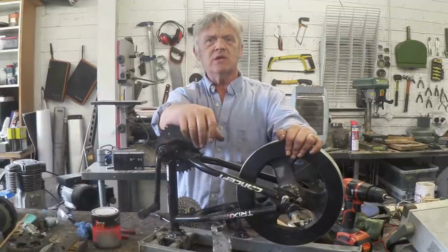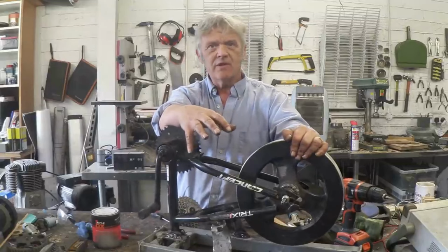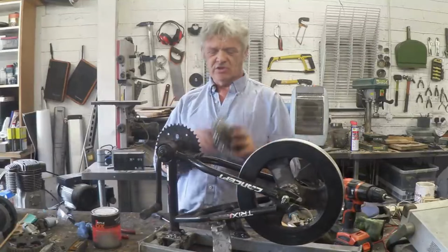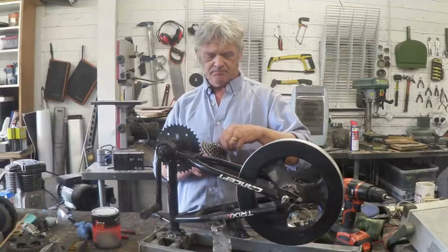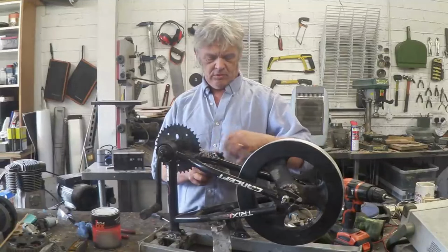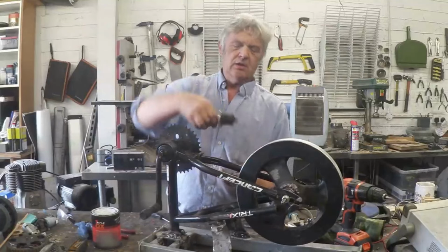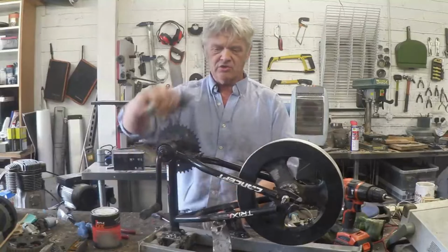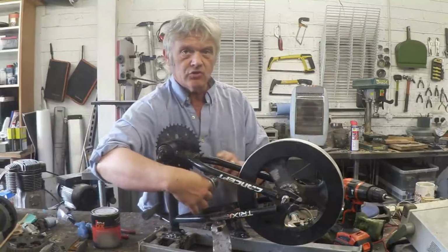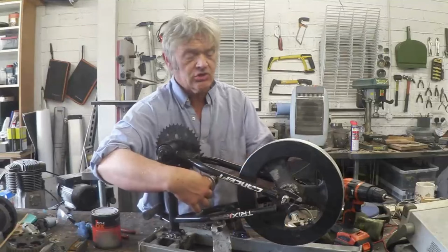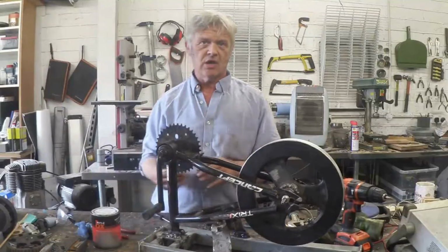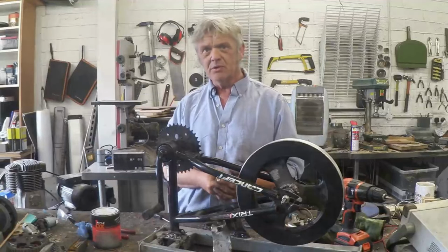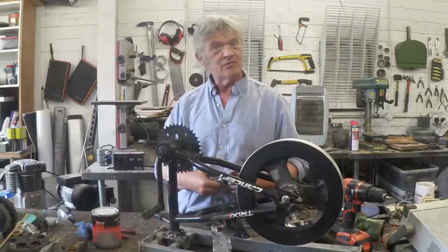As this is all about speed, then that's obviously not really very acceptable. It would be much nicer if I could up that gear ratio, and I do have this thing, which is a cassette. So if I unscrew that, I can remove that whole gear chain like that, and then I can replace one of the large gears with one of the small gears back on that cassette. Fit it in there, I can drive the small gear with this and use that large gear with this, and then I'll get a step up gear ratio, and it'll be in the region of 5 to 1, which is not brilliant, but it's a lot better than it was. So that's what I'm going to do.